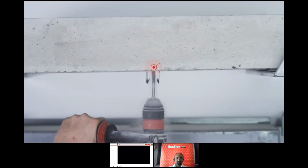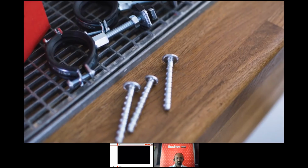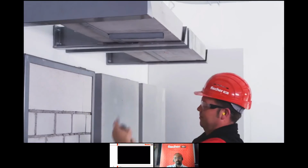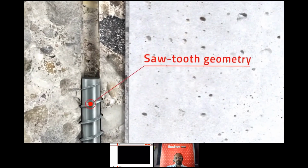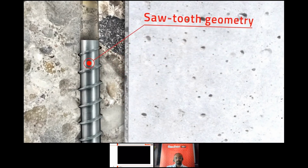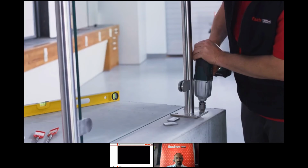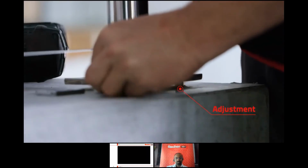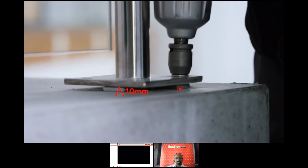Cleaning the drill hole is not required when using hollow drills or vertical installation in ceilings and floors. The unique sawtooth geometry enables fast cutting into the concrete. The special thread geometry cuts deep into the concrete, offering heavy load capabilities. Therefore, fewer anchoring points and smaller base plates are required. Efficient and time-saving. The Ultracut FBS2 can be unscrewed twice for a total length of 20 mm and placed with maximum 10 mm packing below the base plate, enabling the fixture to be adjusted exactly.